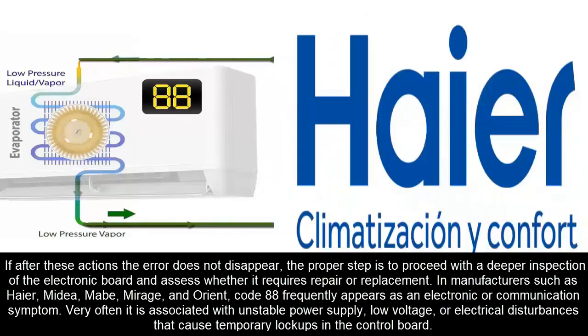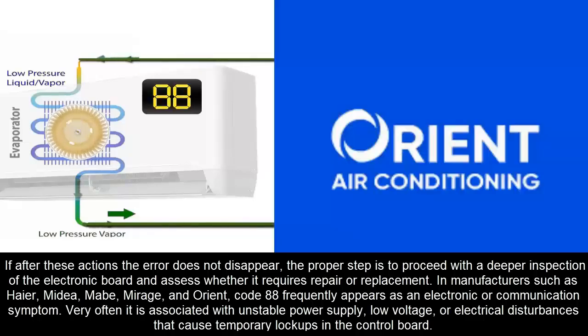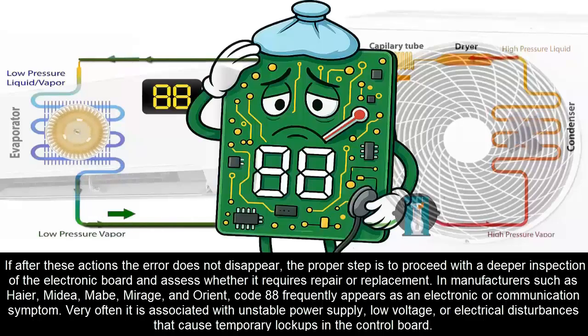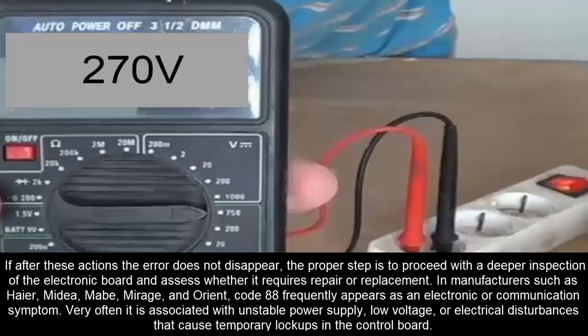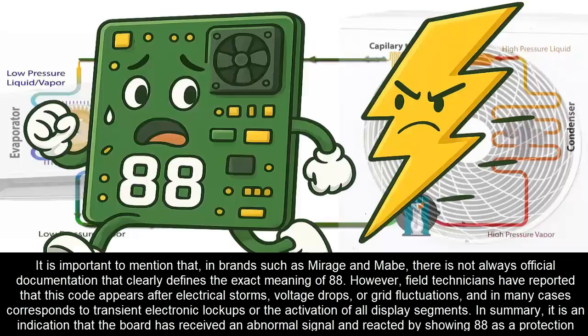In manufacturers such as Haier, Midea, Mabe, Mirage, and Orient, code 88 frequently appears as an electronic or communication symptom. Very often it is associated with unstable power supply, low voltage, or electrical disturbances that cause temporary lockups in the control board. It is important to mention that in brands such as Mirage and Mabe, there is not always official documentation that clearly defines the exact meaning of 88.